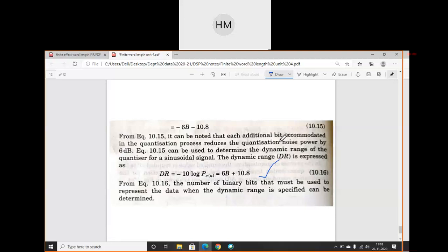So it is not feasible to have n number of different processors for different frequency ranges to execute the same application. What I will do here is use the concept of upsampling and downsampling to get multi-rate DSP. In the same processor, I can get different frequencies. So different sampling rates can be obtained by using an upsampler and downsampler.